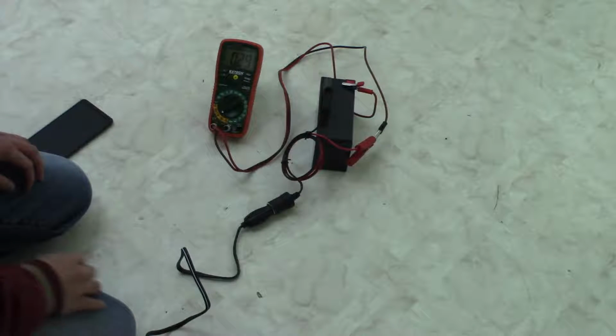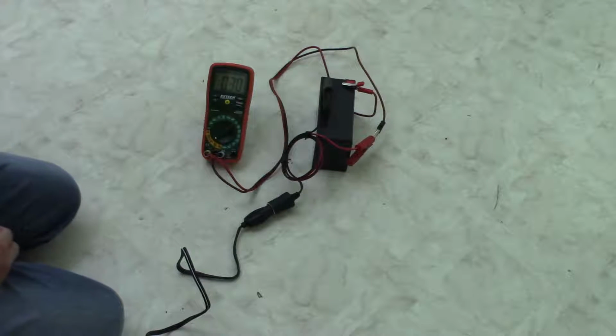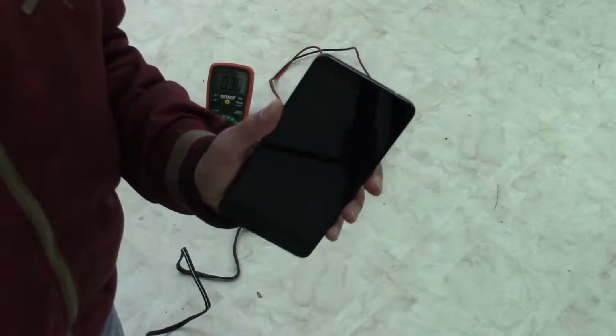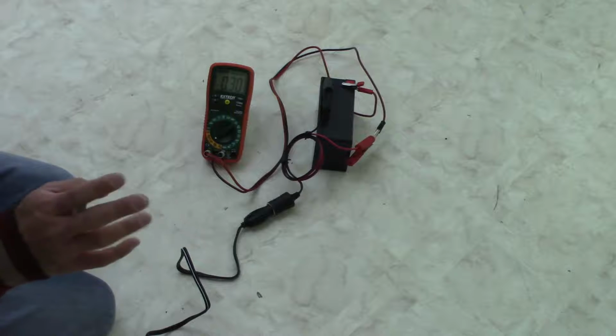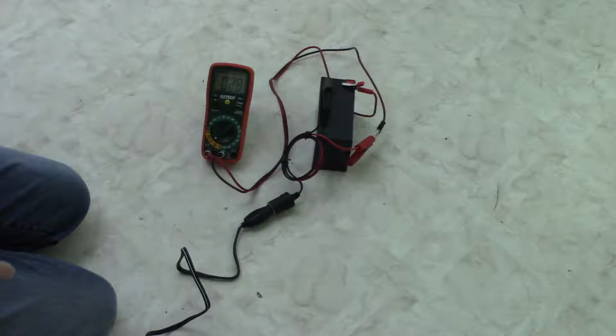Okay, turn it on. So there is 0.3 amps of current. And then you multiply that. I know it was different earlier, but anyway. So 0.3 times 12.5, so 3.75 watts, or almost 4 watts, when we're just running the inverter, and it was like 9 something watts with the camera connected.